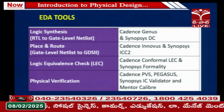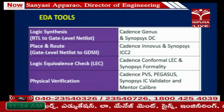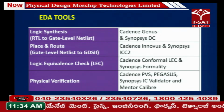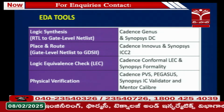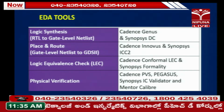Now, coming to the different EDA tools we are going to use in our ASIC design methodology. First one is logic synthesis, RTL to gate level netlist: Cadence Genus and Synopsys DC, Design Compiler.